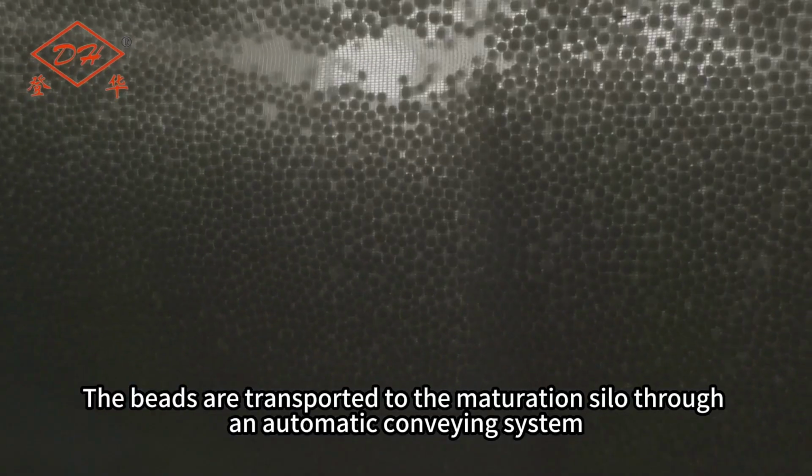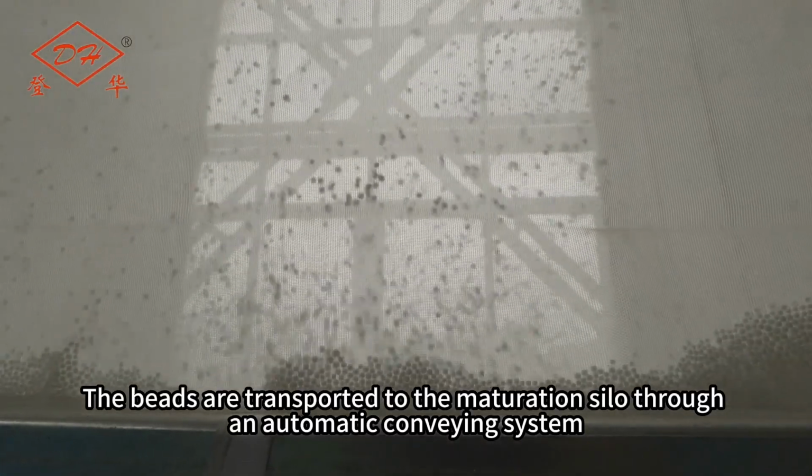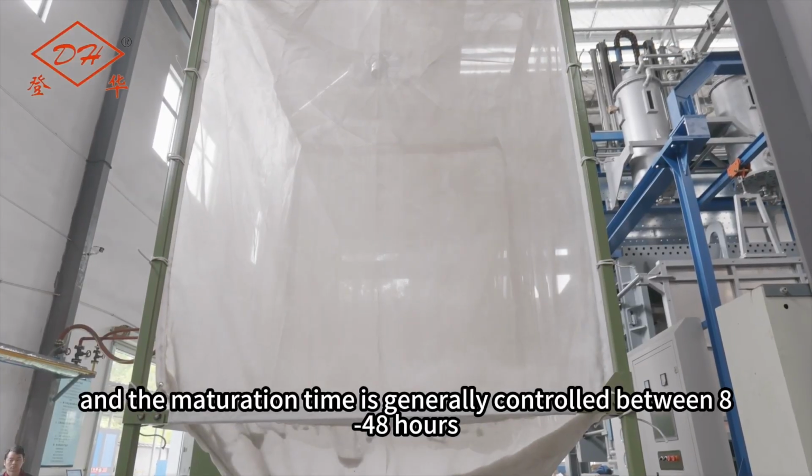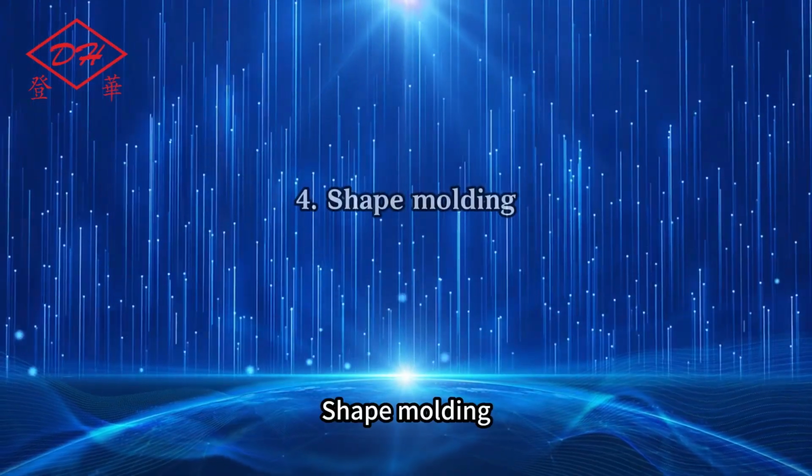The beads are transported to the maturation silo through an automatic conveying system, and the maturation time is generally controlled between 8 to 48 hours. Fourth, shape molding.